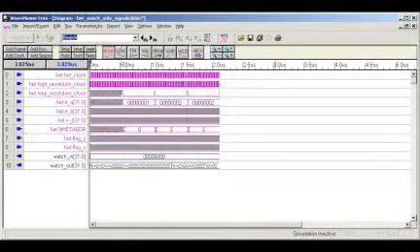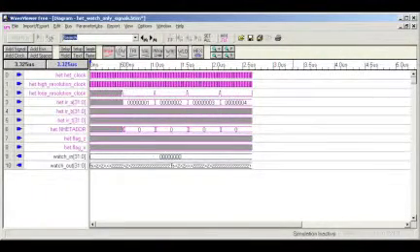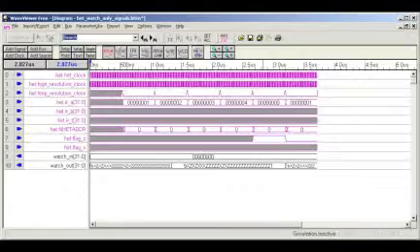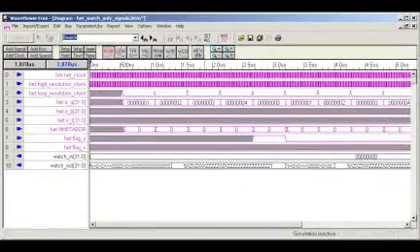The HET signals consist of the I/O pins, but also of the registers, internal registers, or HET memory fields. In run mode, both the high-end timer and the waveform viewer are synchronized. This provides the possibility to visualize signals or memory contents on a cycle-by-cycle basis while the simulation is running.